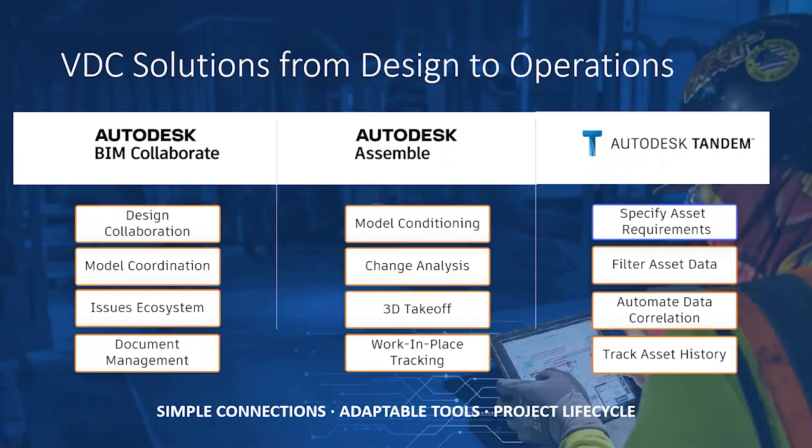Also, and one of the important ones here is model coordination for doing automatic clash detection and being able to understand where those clashes are taking place within the design process so they can be remedied long before we ever get to a point of moving into pre-construction, long before we ever get to a point of breaking ground on the project itself. We want to eliminate all of those issues, number one, so we don't have rework on the project site, but most importantly, that also has an impact on our ability to successfully and accurately do quantification takeoffs and therefore put together estimates as well.